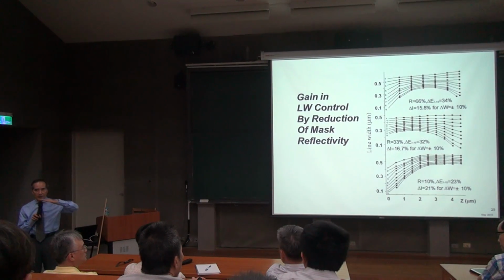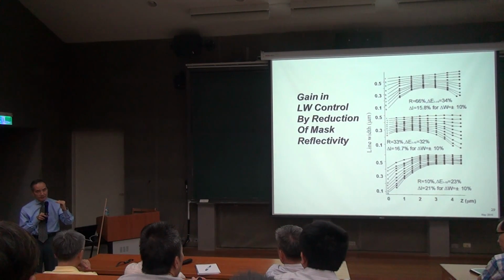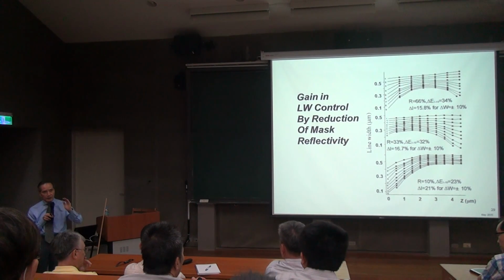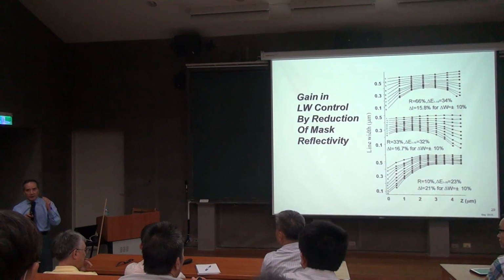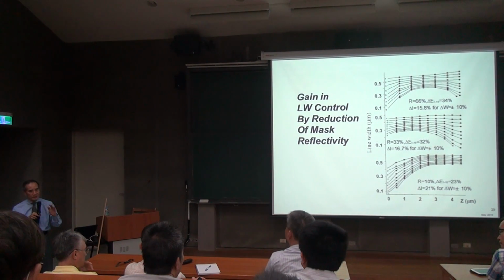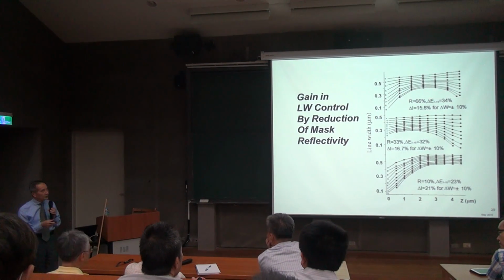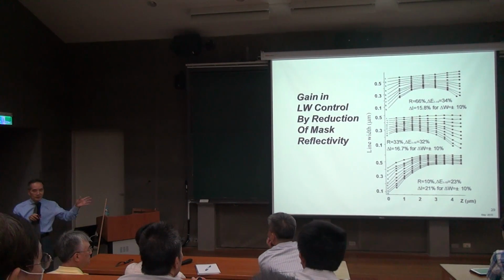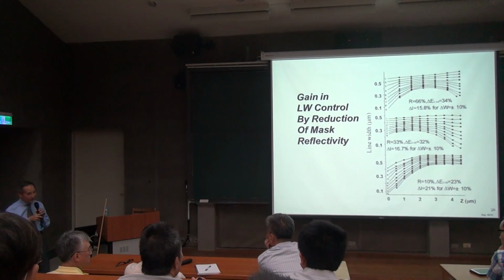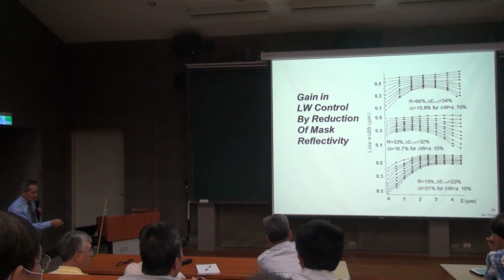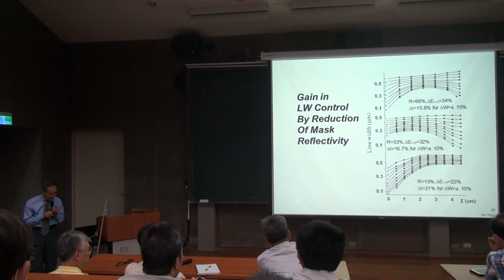We coat a blank mask, no chrome, with photoresist, and we bake the resist until it carbonizes, which is something like 400 degrees. At 400 degrees in air, you burn the resist, it completely oxidizes. So what we did was put it in a nitrogen oven, with no oxygen, and then heat it to 400 degrees. It becomes carbonized. So that's dark carbon, and the reflectivity is 10%. So we used it to prove the point. Nowadays, nobody will get this kind of reflectivity in their chrome mask. Mostly, they manage to have this kind of reflectivity.